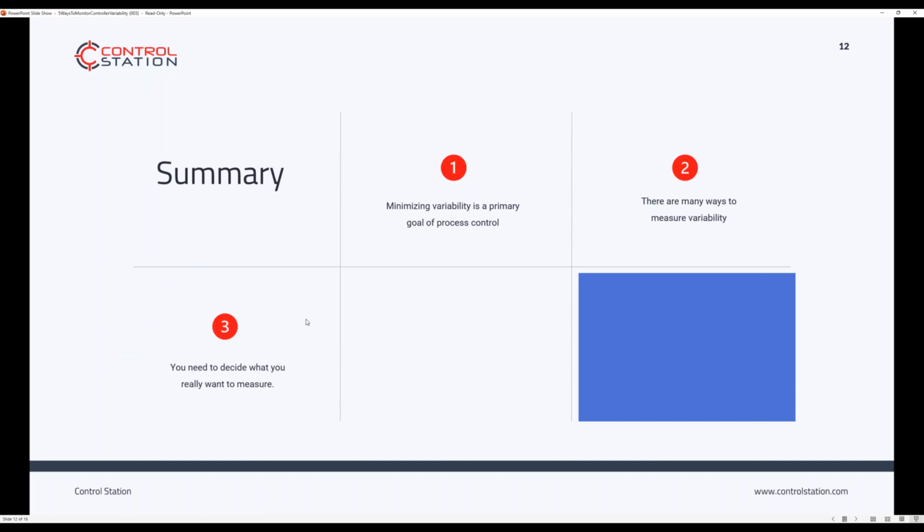Again, even the automation logs are going to provide a lot of useful information to help maintenance prioritize the instrumentation that needs investigation, right? You cannot control what you cannot measure. So that automation log is the very bottom of that pyramid: are your instruments correct? Are you responding to the instrument calibrations correctly?